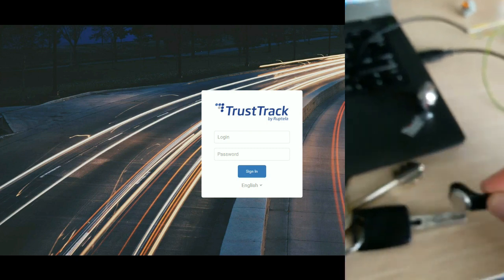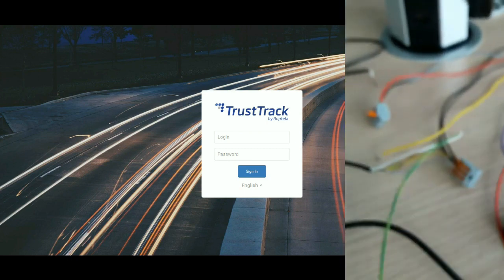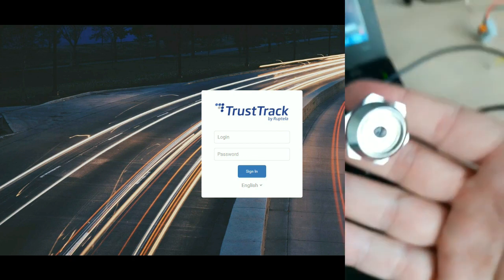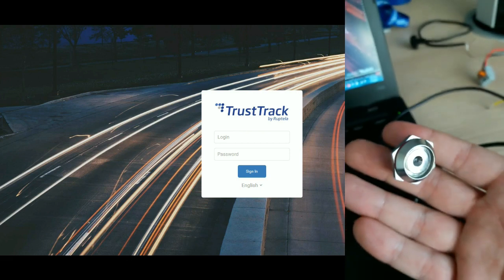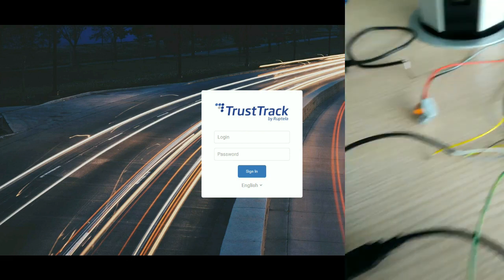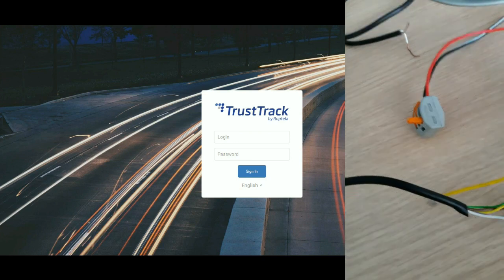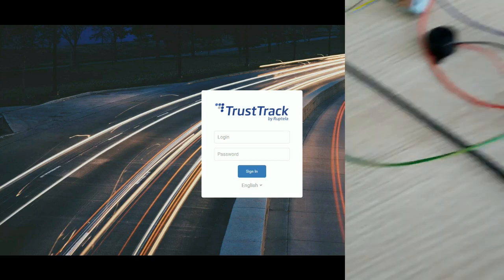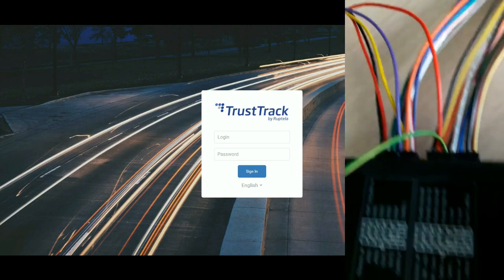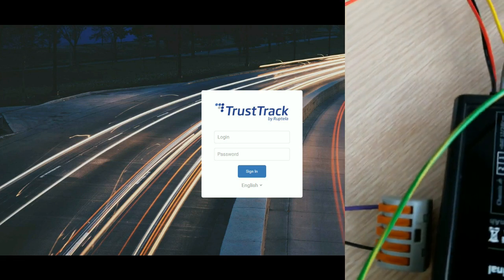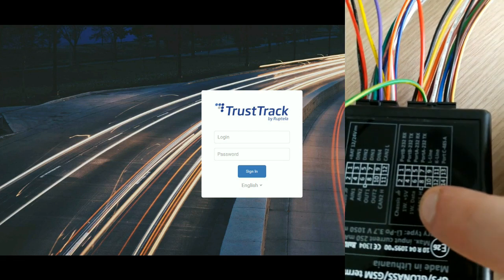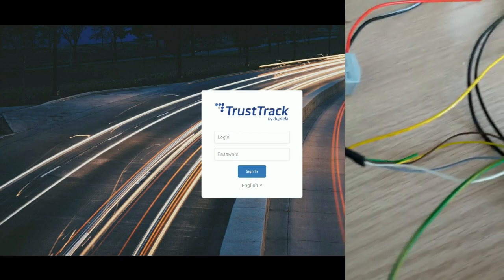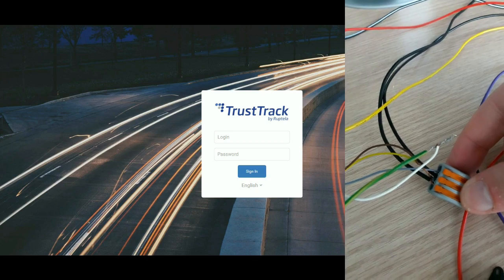Okay, smart iButton. For this case, we have also connected the buzzer, and we are connecting this accessory, which is the iButton. Let's focus. Here we are seeing the connection that we made. We have several cables, and we are using the white one for the one wire, in this case the third one wire data, it's this one. And the gray of the iButton, we are connecting it to the ground.